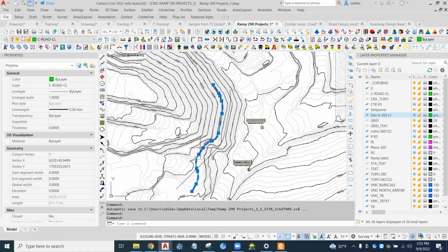That's true. So that line is going to be exactly on the ground. And so it's going to go back into the hillside here, and then the cut to come up to daylight on this backside is going to be pretty steep, steeper than that same slope. But that's great, it won't be in fill. Yep, that's fine. So to do that, this is going to be my outside edge of my road.